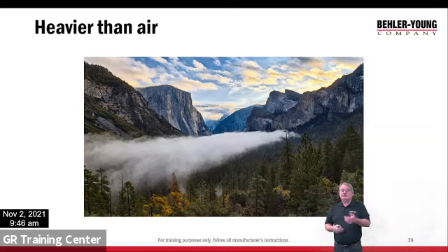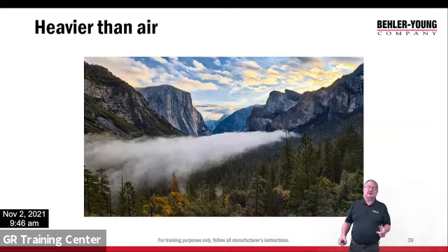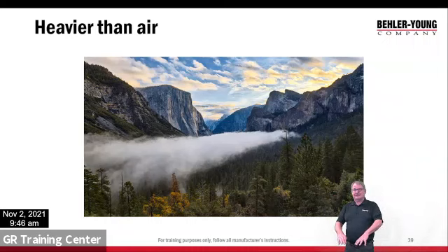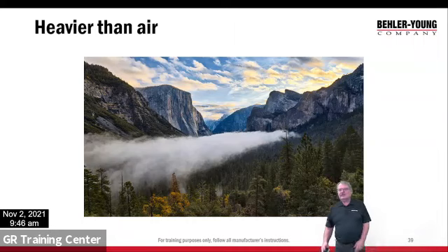Okay, so when dealing with propane, we need to be a little more cautious because it does puddle. It's heavier than air. It'll sink to the floor and start to accumulate, and we can more easily get to that explosive limit. Natural gas is lighter, so it's going to dissipate. It's not going to puddle. It's going to dissipate throughout the house and outside.